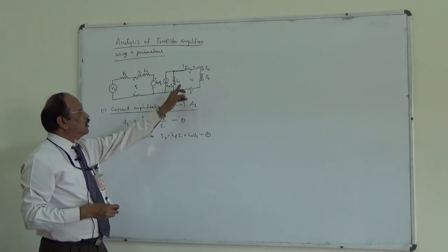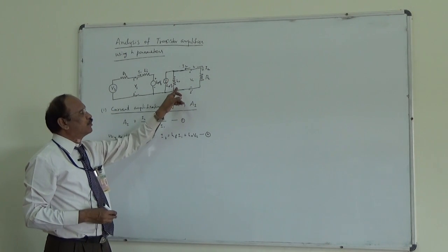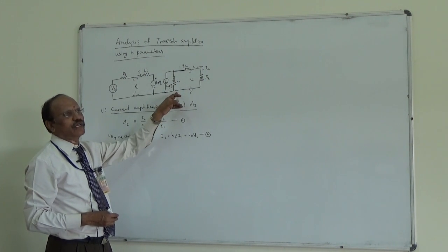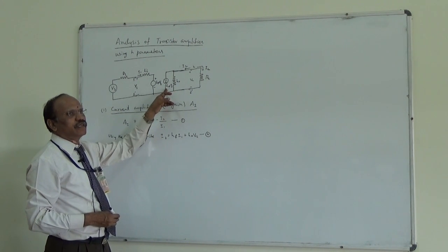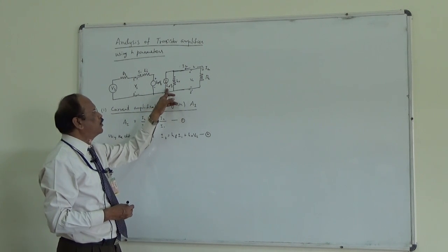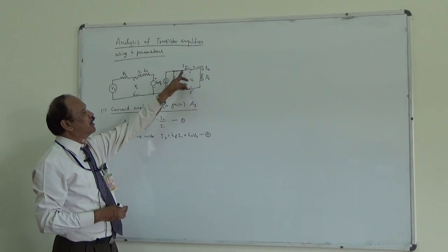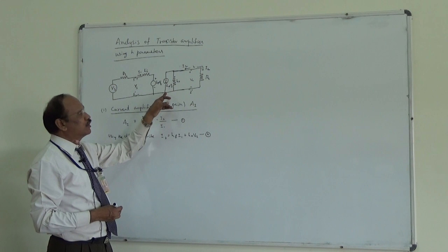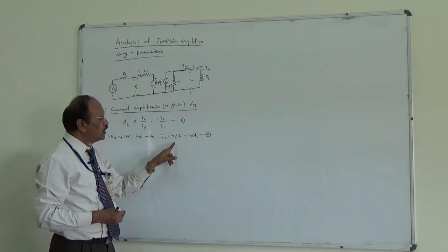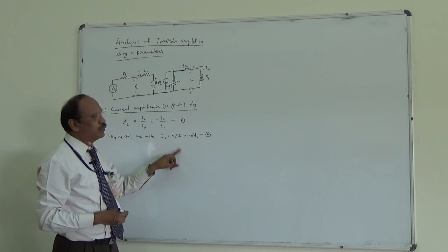See, this H0 is a conductance. If we multiply it with the voltage, we can find the current through this branch, and since the other is already current multiplied by the HF parameter, this I2 current will be splitting into two portions. So we can write I2 as the sum of these two currents, that is I2 is equal to HF into I1 plus H0 into V2.